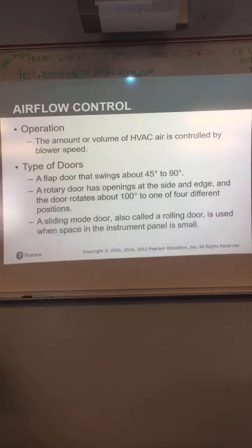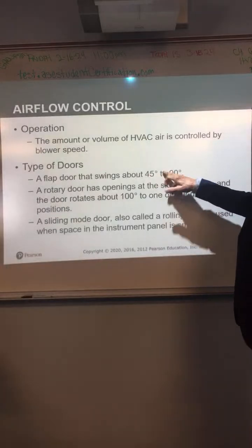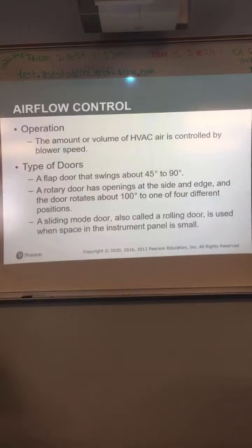Okay. Airflow operation: how much volume of HVAC air is controlled by blower speed. Types of doors: there's rotary, sliding, and flap doors. This is just giving you an idea that not all the air doors work the same, but it's not something you gotta worry too much about. Some of these move certain ways and degrees. Flap door, 45 to 90 degrees; rotary door, could go 100 degrees.